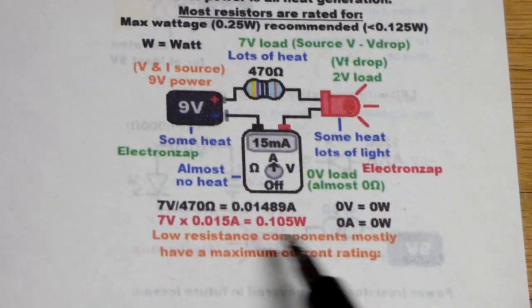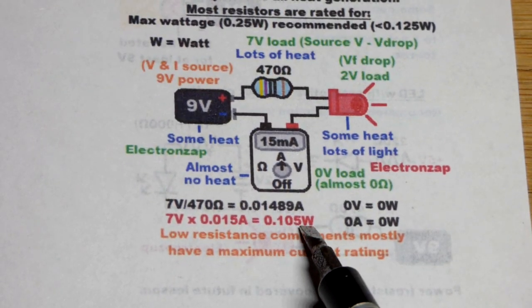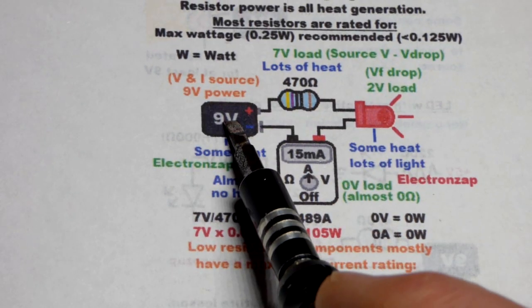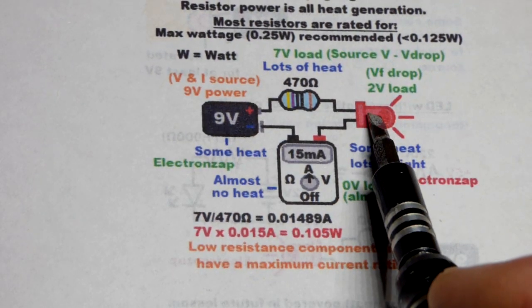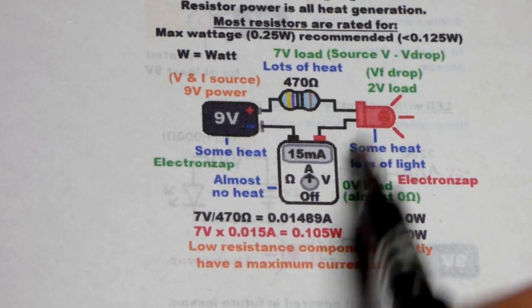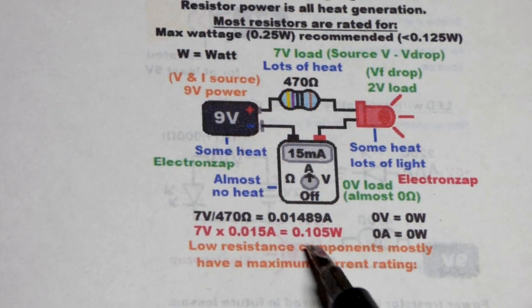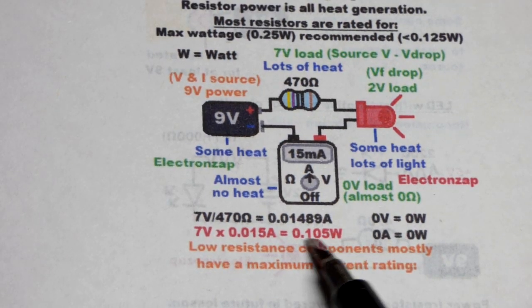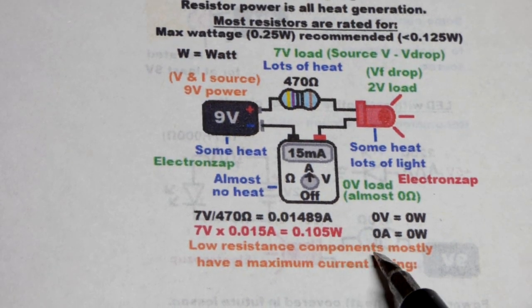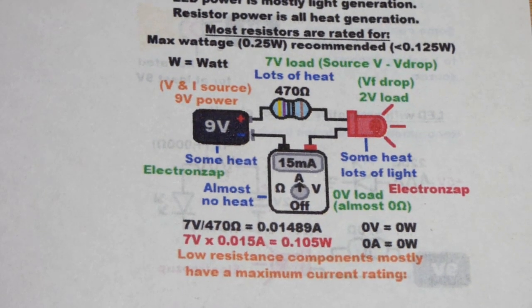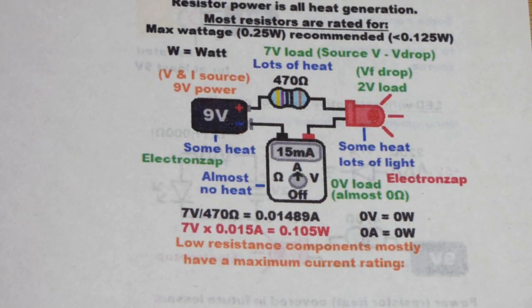But you also got to make sure the resistor doesn't get too hot. So you just use what I just talked about here. You got your supply voltage, whatever else is going to reduce voltage from that resistor, and then you do the math from there and make sure whatever the wattage rating is, generally you want to stay below half of that. So maximum is 0.25.